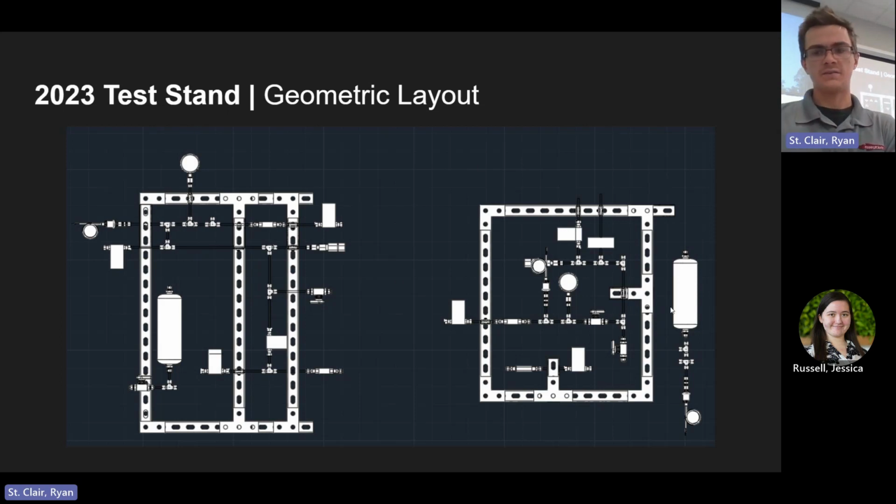And then nitrous oxide, you can see there's this tank here. Pressure goes in through here. It goes through some instrumentation across this ball valve that I was mentioning before. And then the flex line would go from here to here. It would push that nitrous oxide down. Again, there's that thermocouple that we need to detect when that nitrous oxide reaches 0 degrees Celsius, because then you start to fill it not as a gas, but as a liquid.